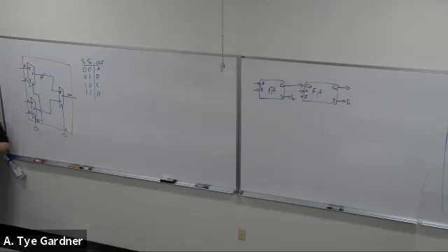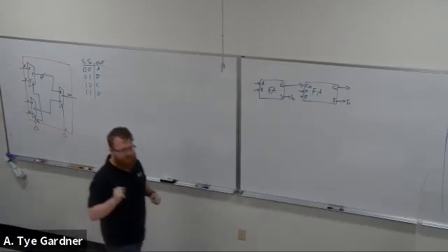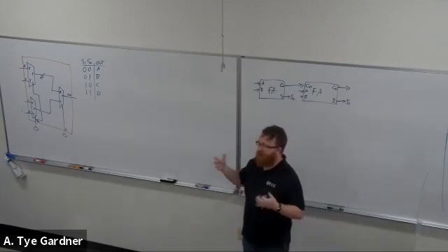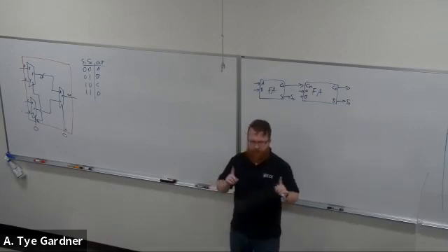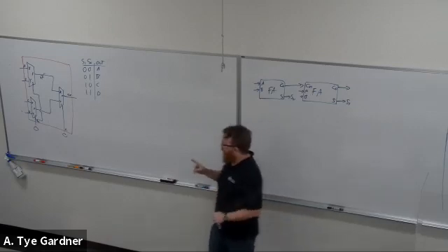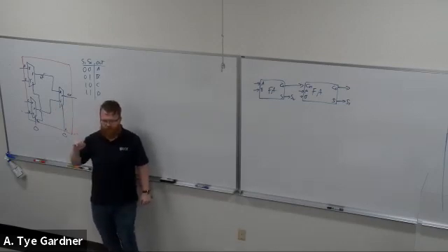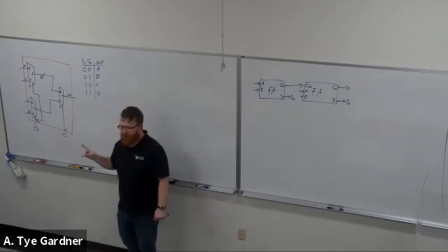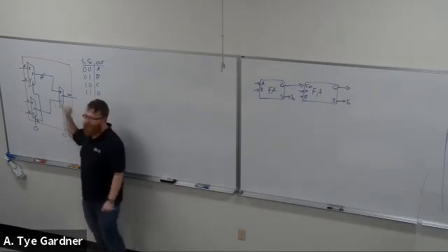Ta-da. So how does this relate to VHDL? Well, remember that I said that there are 2 different kinds of structures, we'll call them architectures, that we're going to use in VHDL code. The first is behavioral. It describes how one of these muxes works. Okay? The architecture that is structural, so behavioral is how it works. Structural is how they are connected.